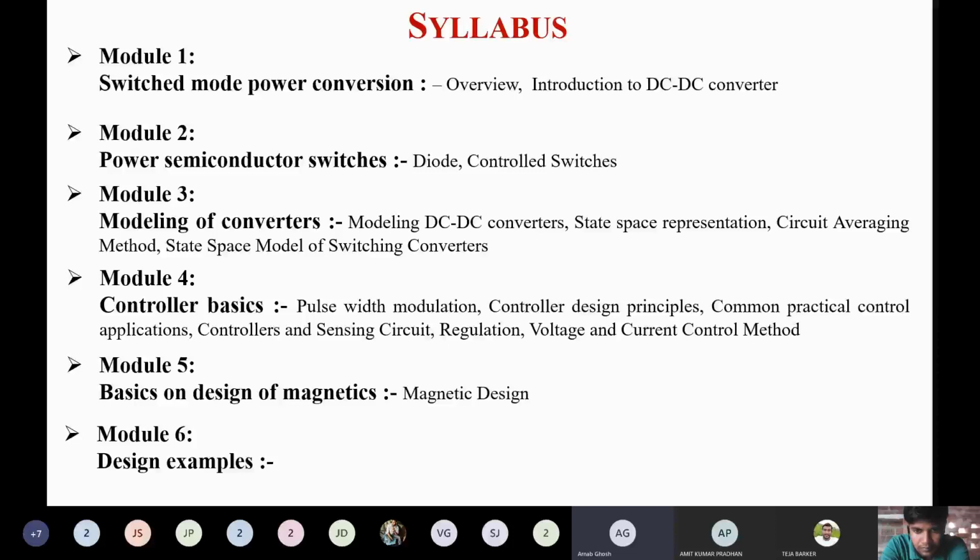Okay, that pulse will be passed through the driver circuit. You are not able to give that pulse directly to your MOSFET switches, or any of the switches. There is a standard driver circuit, because the pulse does not have sufficient voltage and current strength. So sometimes you have to amplify the voltage and current strengths. There is a control circuit using basic analog circuits in the driver circuit to drive the solid state device.